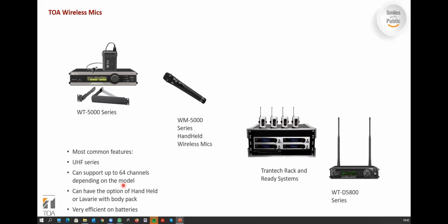What it simply means is I can have a conference setup. I can have a microphone setup where I'll have 64 of these microphones and 64 of these handsets. And each handset can run at a separate frequency to its mother tuner. So in other words, I would have 64 microphones in one particular venue, all working at the same time without crosstalk, without cross interference. That is very critical. Otherwise, if we don't have this separation of the frequencies, we're going to be in trouble.